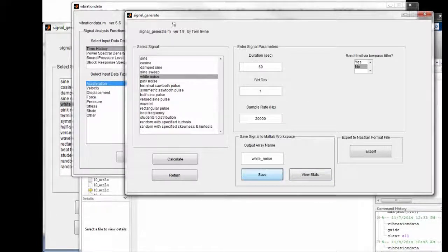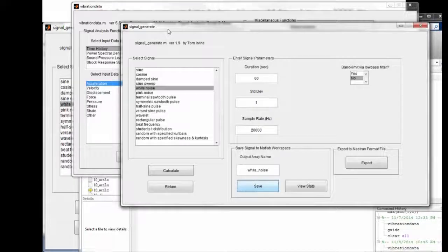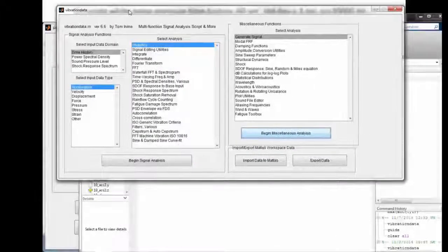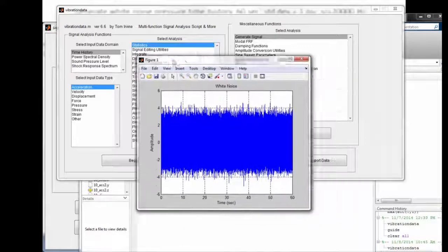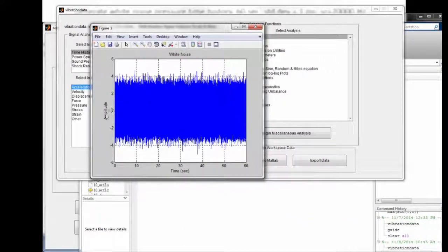Then that's saved. So what are we going to do with that next? Well, that's going to be our pressure time history, our sound pressure time history. And maybe I'll make a few other remarks about this. So this is really pressure in psi along the y-axis. And you see this value 0 here, the 0 baseline. This is actually referenced to the ambient pressure.